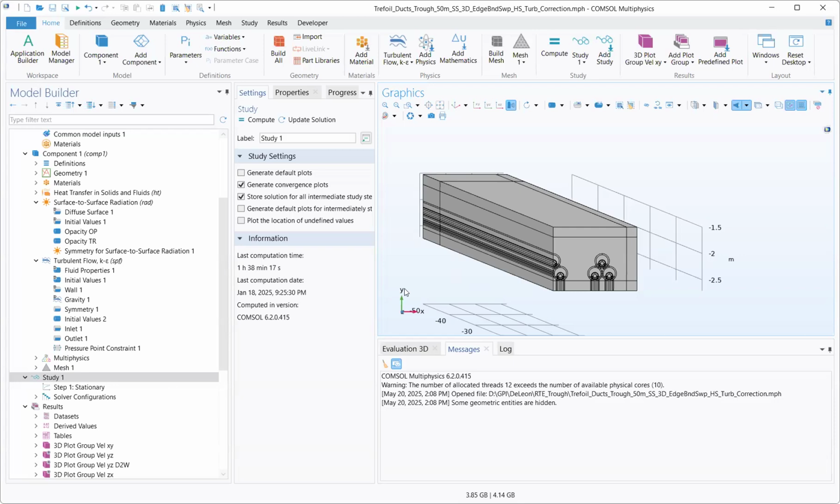I have a follow-up question. For the case you showed us, you showed it for 40 years. So for that case, you just set the time step really large to simulate the 40 years? Well, for 40 years, I use a time step of a fraction of a year, like 0.025 years. So almost divided by 50 or 40, something like that. Typically divided by 50. So 1 year divided by 50, right? Okay.